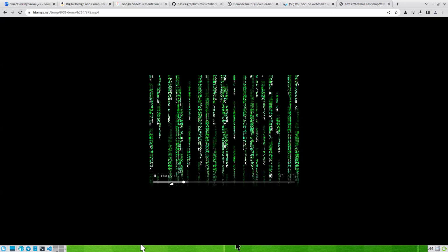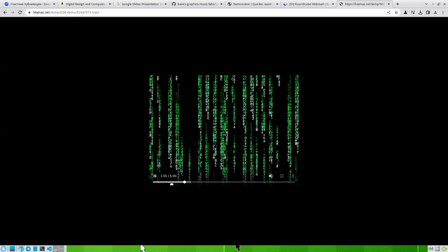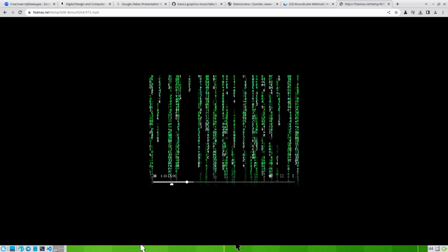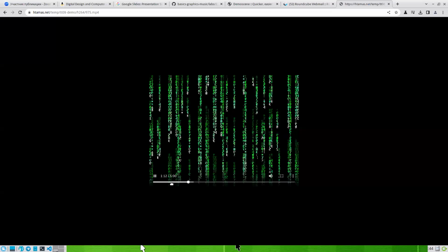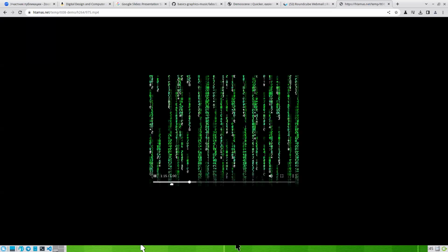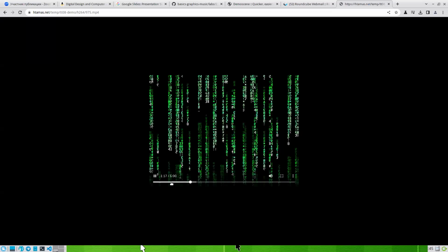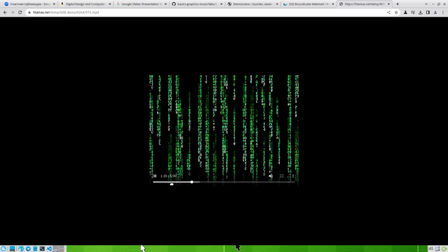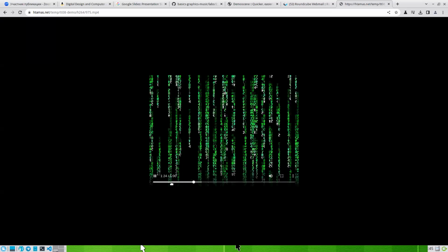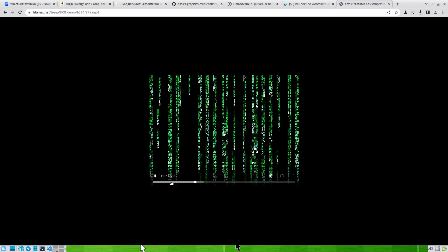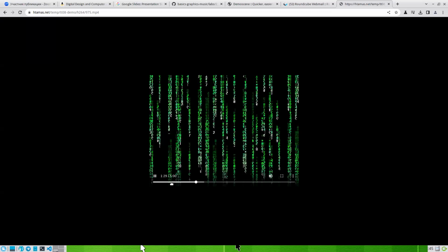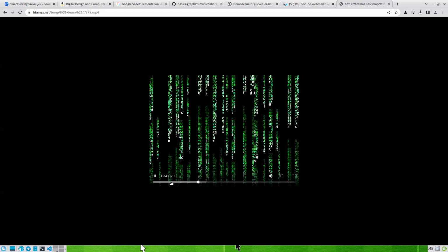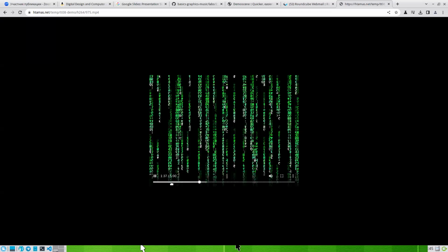Did you install Quartus? Yeah, absolutely. Where is Quartus installed? Home Altera 13.1 SP Quartus. Oh yeah, but you are using an older version of Quartus for the older boards, and this one expects to use the new version of Quartus. In principle you can use the older version, but it expects to find the new version inside Intel FPGA. But you don't have an Intel FPGA directory.